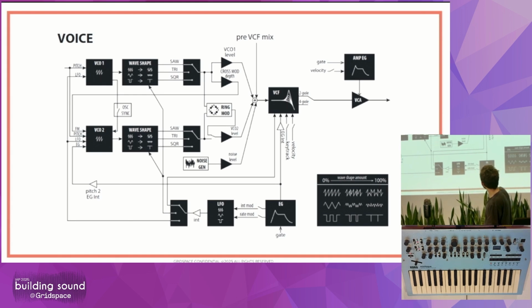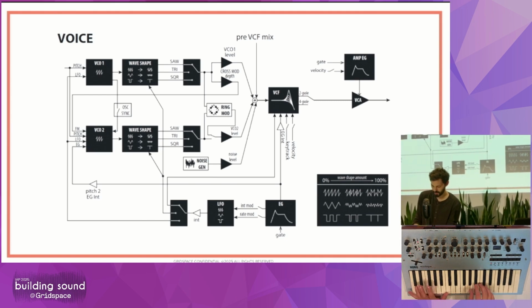And then this is the envelope generator, which you can see feeds into multiple things. So the pitch one, which I just showed, is this connection here, which goes back to the pitch of the voltage controlled oscillator there. And then the other thing that the envelope generator can impact is the low frequency oscillator, which I'll show is actually one of the most fun things.